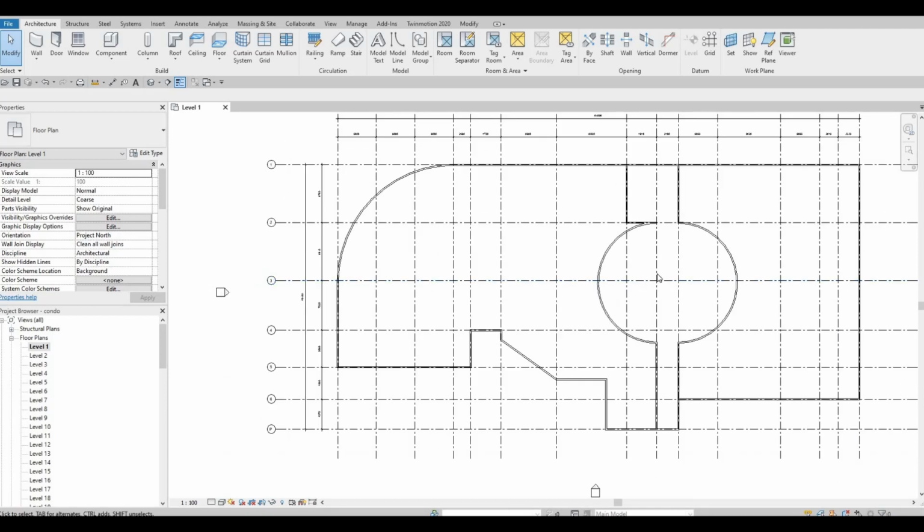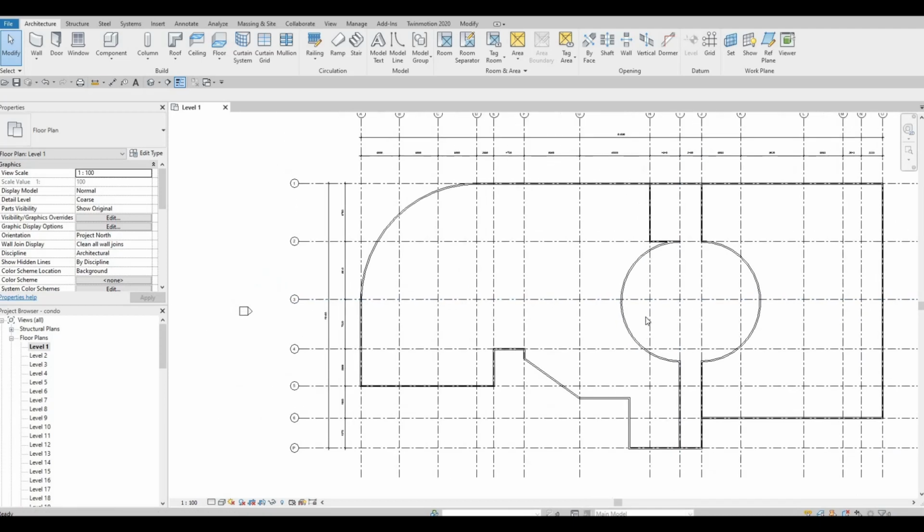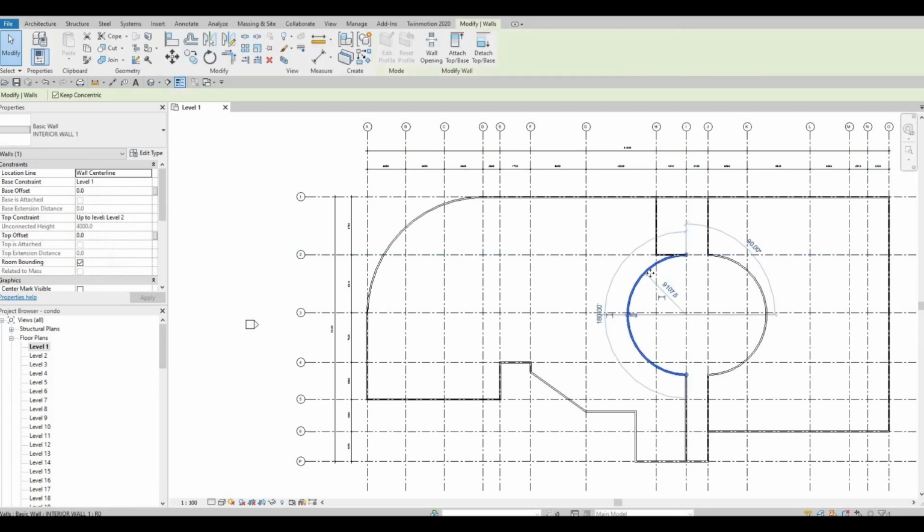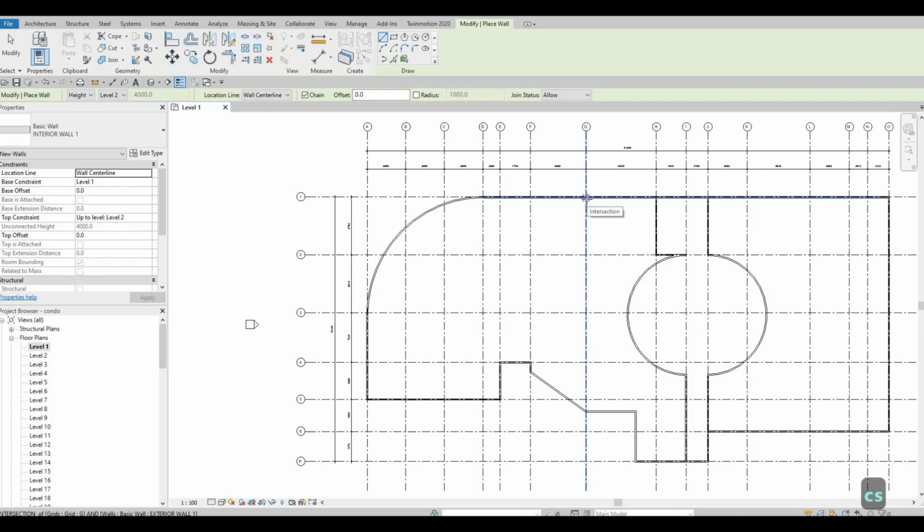So this will be our lobby or atrium. And then now what we can do is we're gonna have this. So click on this one again, the interior wall, CS, and then from G right here, click right here at G2, and then just connect it slanted at 20 degrees connected to the atrium.